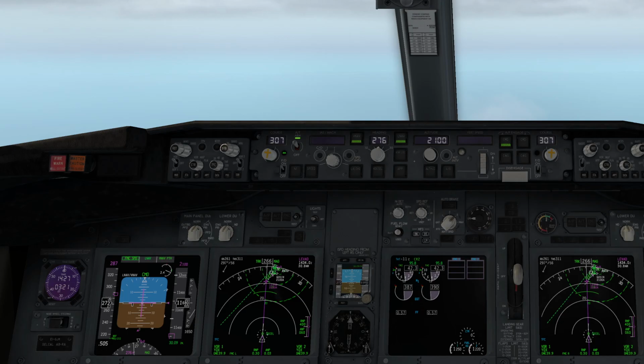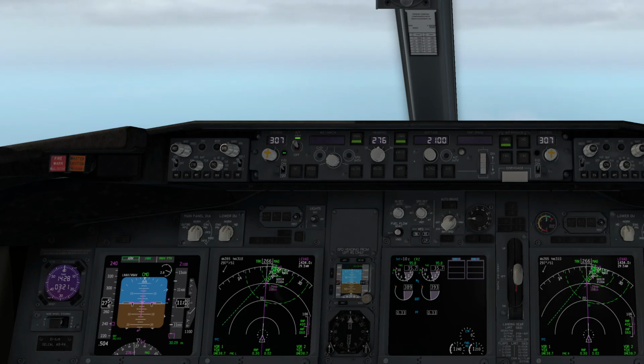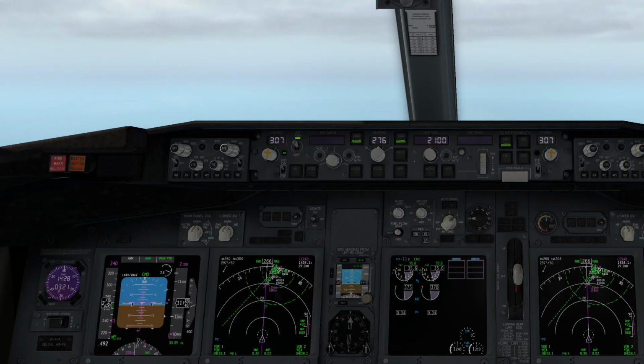Bless you. Passing the decel point, we will see, oops, yeah, target speed is now 240, so thrust idle reduced, and we reduce also the descent. It's now 900 feet. So nearly leveling. Descend at 400 feet per minute.